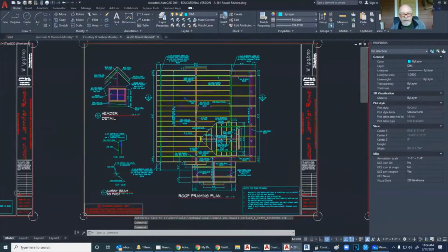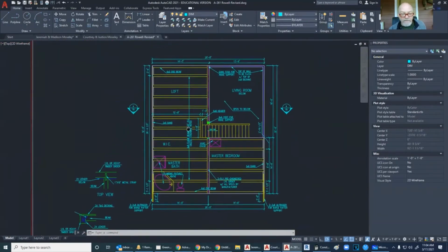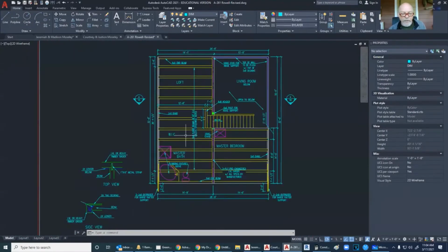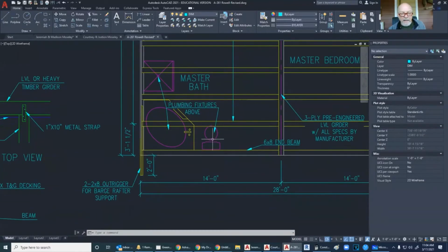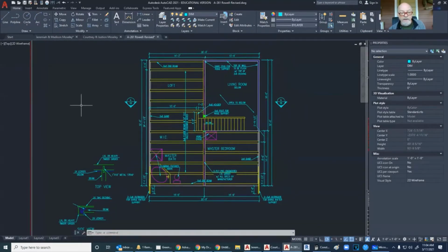So we do roof framing plans where we tell them where this is going to be. And actually we do floor framing plans, second floor framing plans when we use large timbers. So these are 4x8. Actually, these are 6x8 timbers. So we have to plan ahead to find out where our baths are going to go, where our toilets are going to go, so that we don't have to cut one of these. So if we have to shift this one way or the other, we can do it in the plan on paper and then send it out, and they can follow this to lay it out.